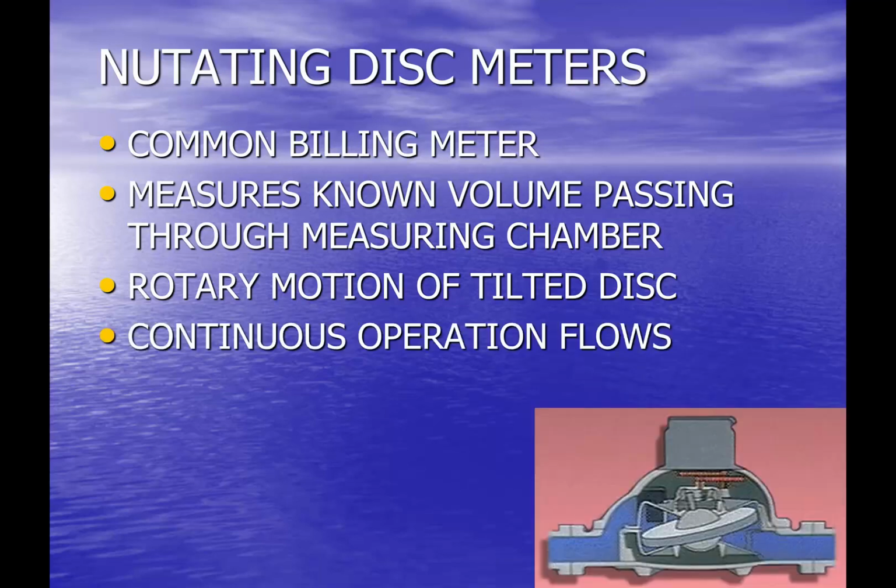They're used for design, at least for relatively continuous operation. The goal is that they are operated typically around 50% of their maximum capacity. Using continuous flows at the maximum capacity of the meter will damage the meter. It'll cause it to wear sooner than it should and can contribute to significant accuracy issues.